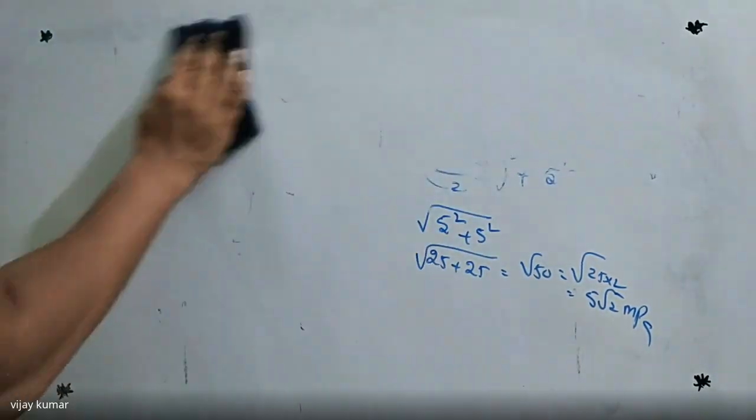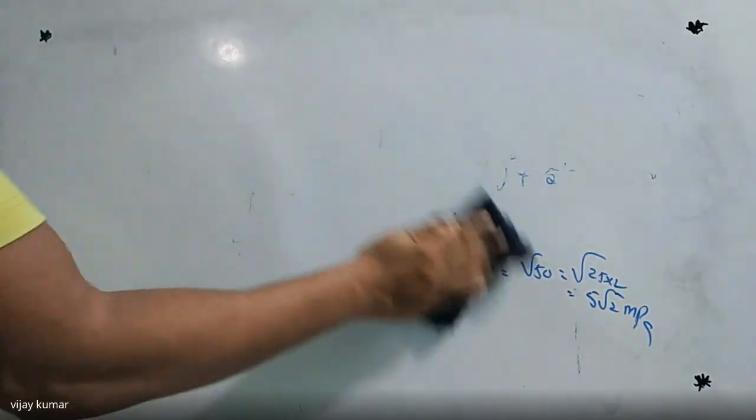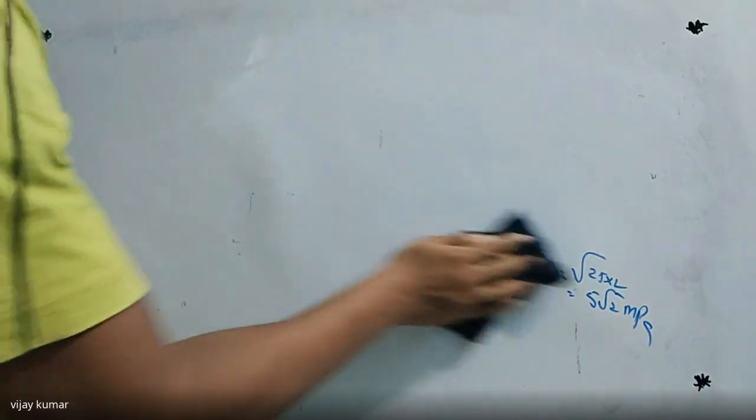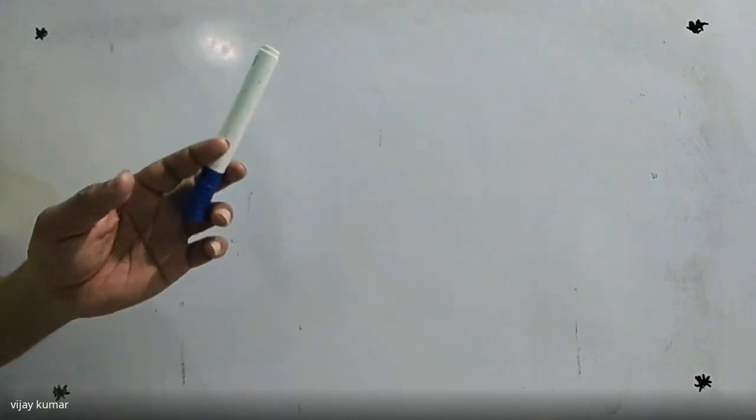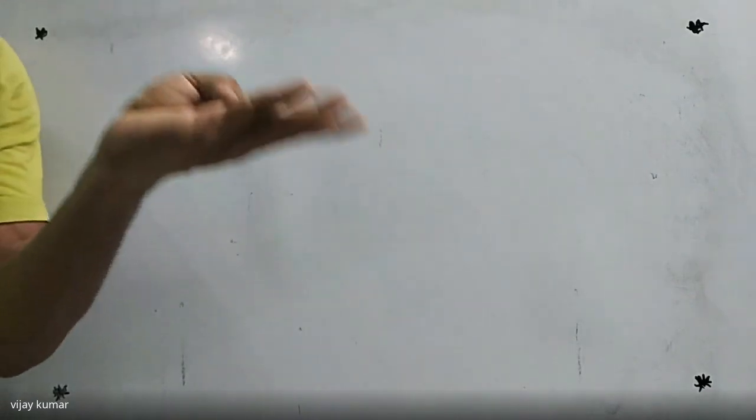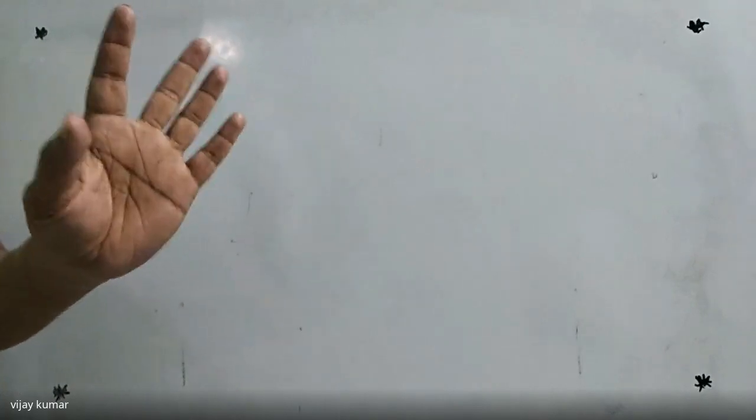So first of all, if any question is given on a complex state of stress where you want to find the maximum and minimum principal stresses, we have to identify first of all which case the problem belongs to, whether it is uniaxial, biaxial, shear, uniaxial and shear, or biaxial and shear. Then only we can calculate all the values.